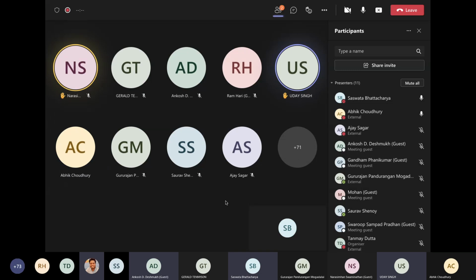What you are trying to say is that at certain temperatures some precipitates have formed and they're growing, and then you go below a certain temperature and you get finer precipitates. That's what you are talking about? Yes, sir, absolutely. And actually, sir, for example, for Inconel 718, gamma prime and gamma double prime both are precipitating in a particular temperature range.